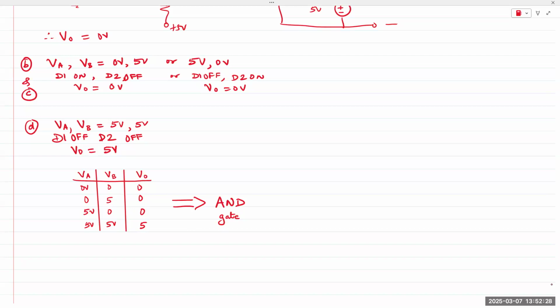And practically, that's why we have fuses, right? If you have a short circuit somewhere, it means it's bypassing all the resistors, everything in the pathway that could slow down or reduce that current. So a short circuit simply means you bypassed everything. It's a huge amount of current flowing through. A real life wire will have less than 1 ohm resistance, so even if you apply 1 volt or 2 volts across it, it's going to heat up.